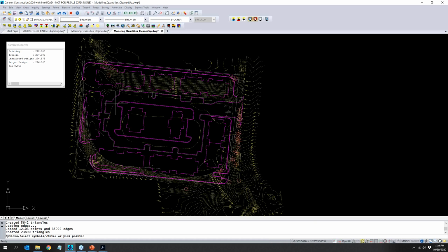Okay. So you can kind of see here what the different elevations are based on where my mouse is sitting. So where I'm sitting now, it's taking into account topsoil stripping, my finished grade elevations, and then 10 inches of subgrade, I think. Here it's taking into account topsoil stripping and then topsoil replacement is all. Any questions?